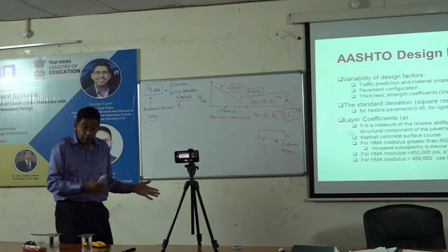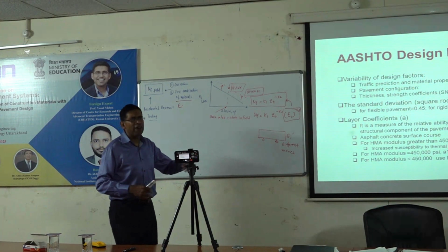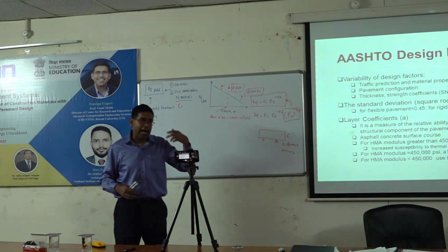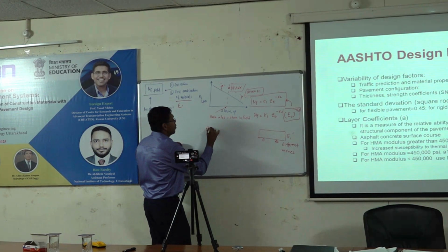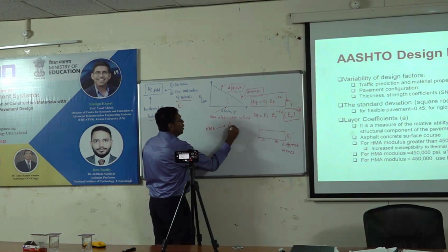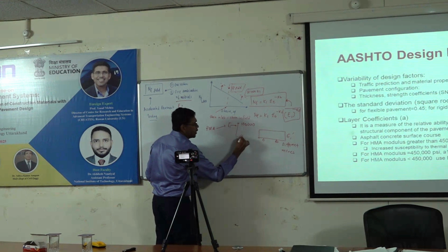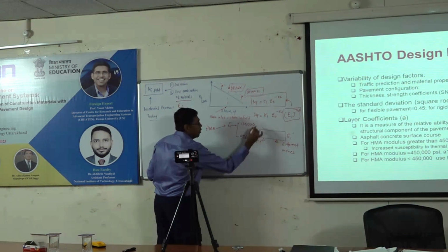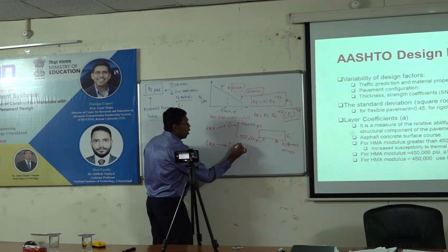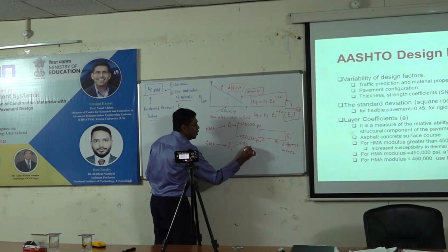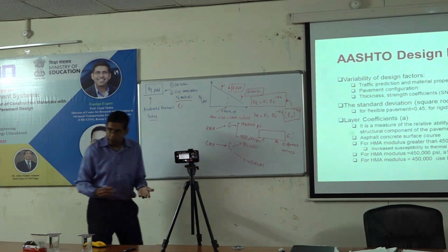But all of this takes away from some other resources. So then you have to be very strategic. Does it really matter if I increase the air voids, add polymer modified binder? This is a very good question. So for example, for HMA, hot mix asphalt, my E1 value for a given temperature changes from 100,000 to let's say 500,000 psi in a given temperature range. Now SMA might change E1 from let's say 80,000 to 450,000 in that range. Correct? It's a different mix.